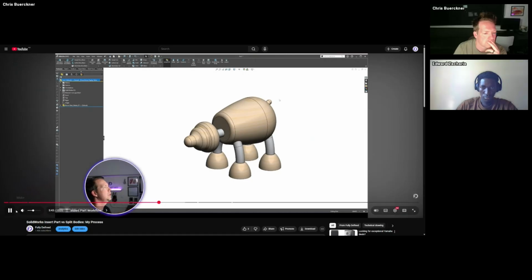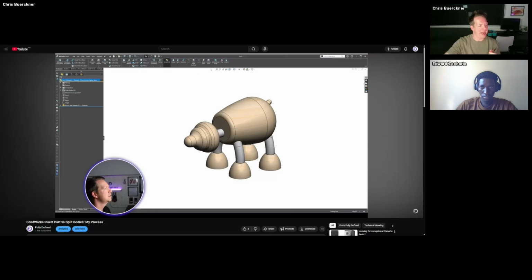Well, what we would do is next, I just want to touch on this point quickly. We know in SOLIDWORKS there are multiple ways of achieving the same result usually. So if you have a master part file, there are a few ways of splitting bodies out into separate files. One of those is to use the split bodies feature. One of those is to use the save bodies feature. Another one is to right click on a body in that folder and go insert into new part.